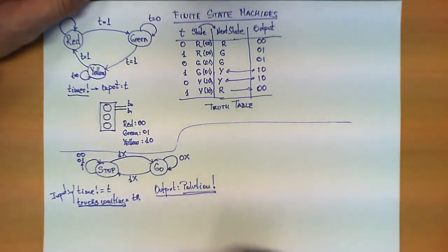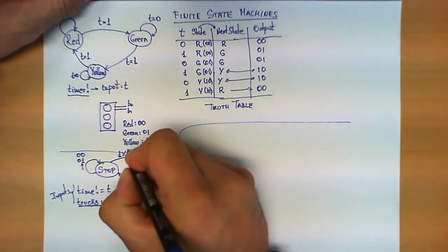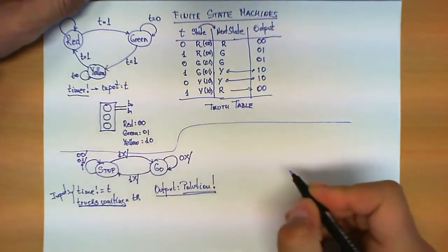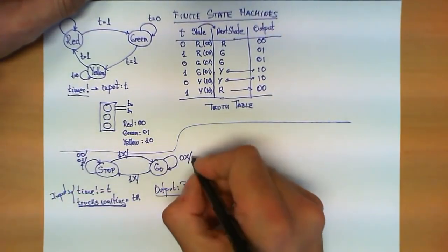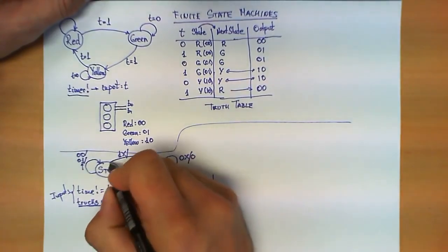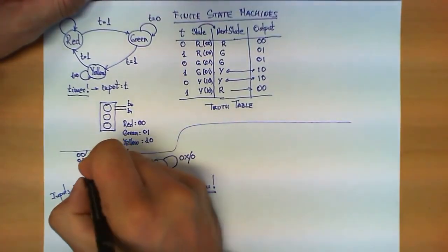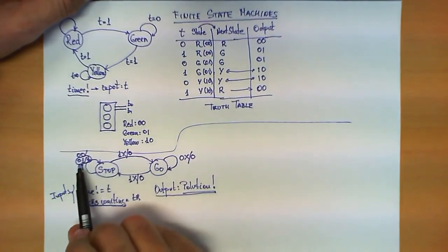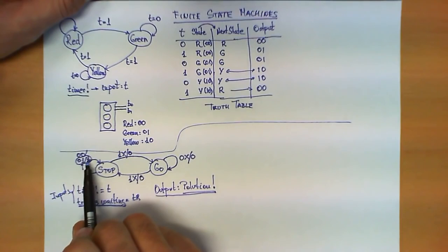The way we're going to represent this functionality here is by attaching to each one of these inputs, or each one of these transitions, the value of the output. Now, when is pollution detected? Definitely not when the traffic is going, not when I make this transition, not when I open the lights so the traffic can circulate, but precisely on this condition. When the traffic cannot circulate yet, I detect trucks waiting, pollution is 1.